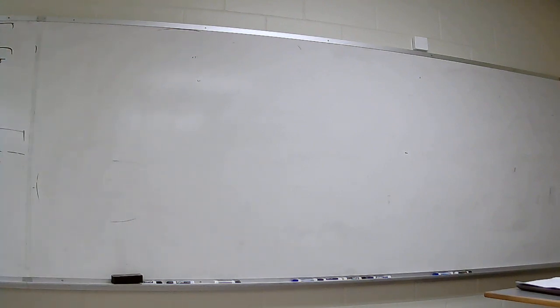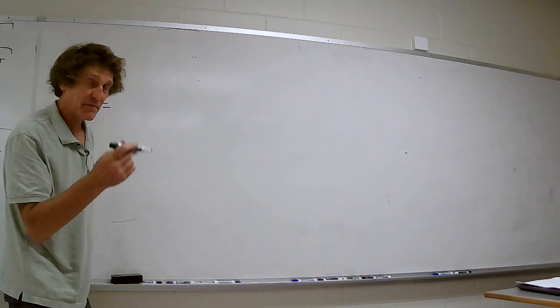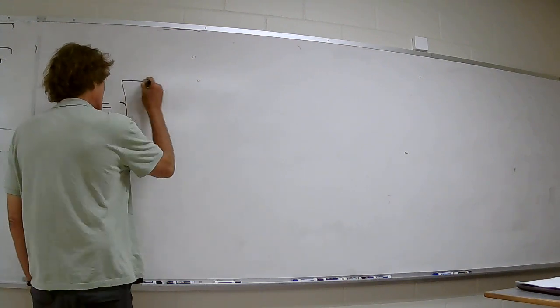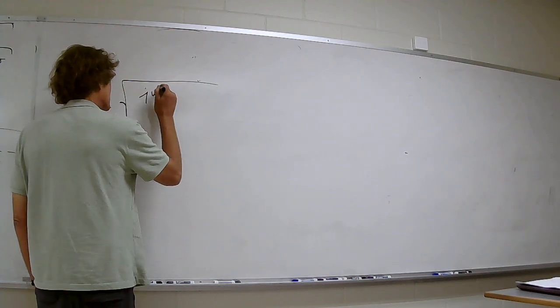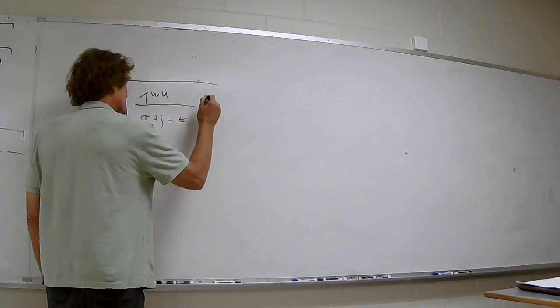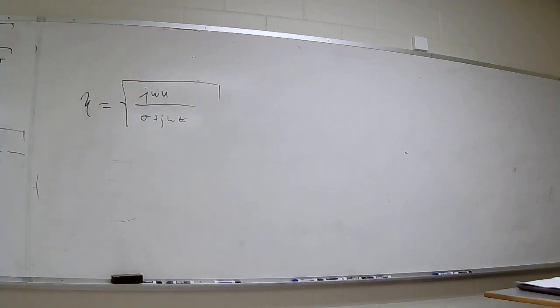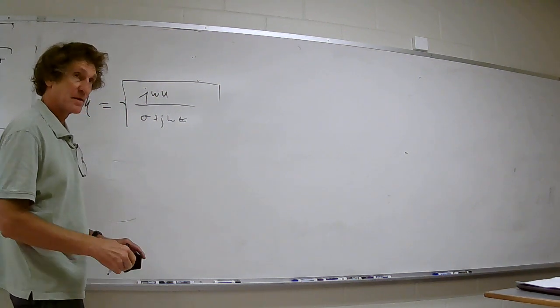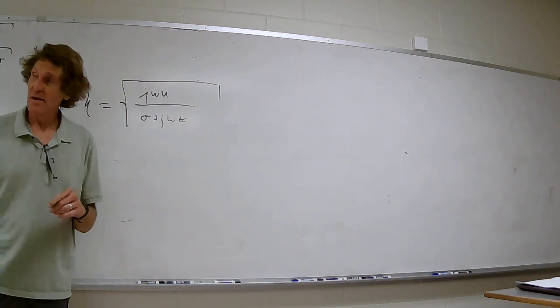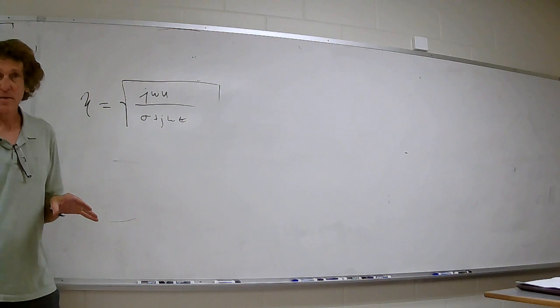So, what is the characteristic impedance of the media in general at a given frequency? It's the square root of j omega mu over sigma plus j omega epsilon. Yes, that's it, right? Now we made the assumption it's a very good conductor, didn't we? Yes. So what do we do? The sigma is much, much greater than this, so j omega epsilon is irrelevant. All right, everybody watch this. Make sure you don't miss this, because it'll be on the quiz.